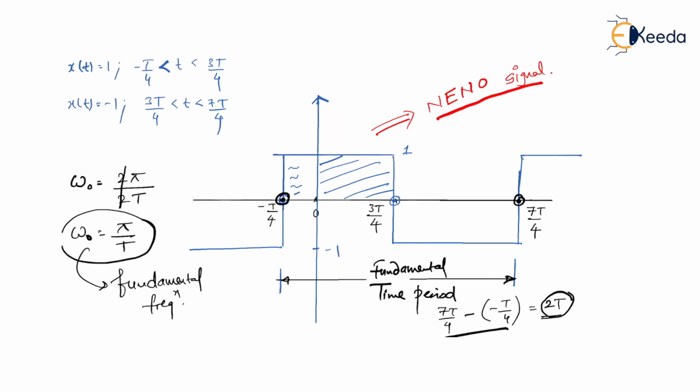Now the question is, if I want to get only sine term or cos term, the only thing is that I have to convert the signal into an even signal or odd signal just by using the time shifting property. I repeat, we have to use the time shifting property. So let me tell you, this is x of t. A signal could be an even signal if it was like this. Am I right? But right now we have lesser content on this side and more content on the right hand side. So if I want to convert it into an even signal, I have to advance the signal, because I have to shift the signal a little bit to the left. So let us determine by how much quantity we need to shift it to the left, so that on both the sides we get common area. Am I right? Because this is what is required to make the signal even.